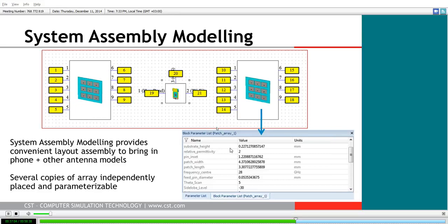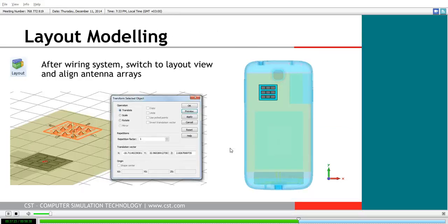Now, because we're going to be aligning these things, we're basically mounting them structurally. There's no electrical connection beyond those we'll form with 3D placement. All we need to do is just wire in external Design Studio ports to each of the wire terminals on these Microwave Studio blocks to make the system complete. After we have our design canvas taken care of, we need to define the relative alignment, how these different 3D models that we're bringing in are oriented to one another.